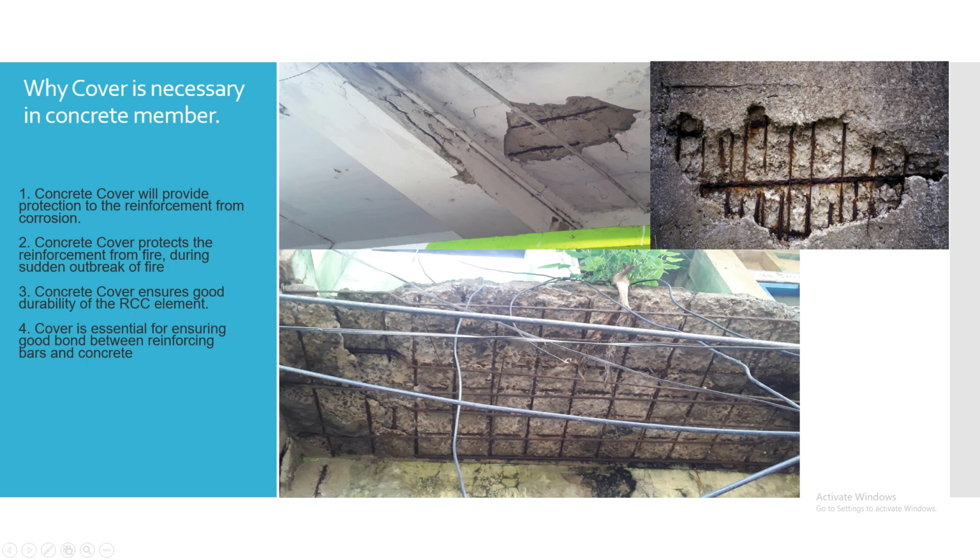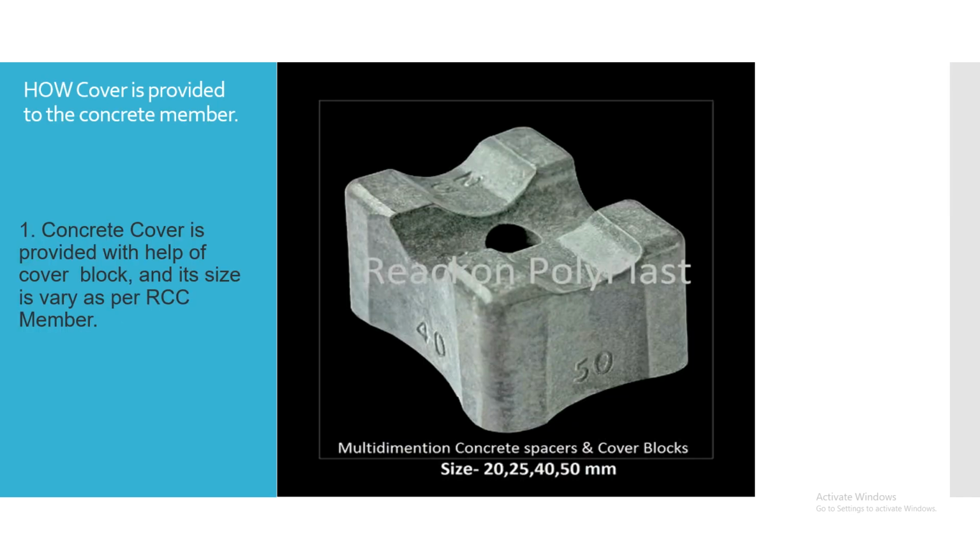So therefore cover is necessary: to save from corrosion, to save from fire, to increase the durability and to increase the bond between steel and the concrete.